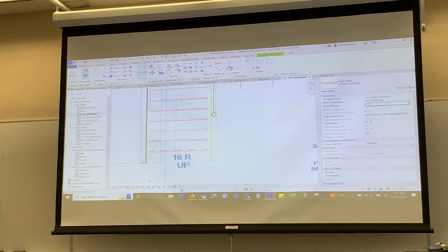There's the stringer. They put a 1x4 in here so that before this is drywalled, you can drive fasteners in here. Screws work best. That way the stringers don't bounce and the stairs don't creak as much. Good builders do this. Shoddy ones don't, and the stairs make noise. But they leave room in here, a little more than a half inch, so the drywall can tuck in. You just slide it in between. Then there's usually a little molding in here to take care of anything. And then this gets capped on the top, and it looks pretty. Or maybe it just has carpet wrapped on it. There's a billion different ways to trim that out. But that's how that works.